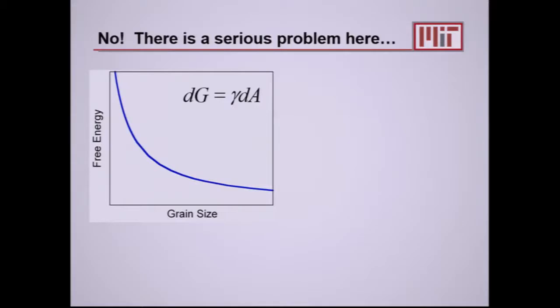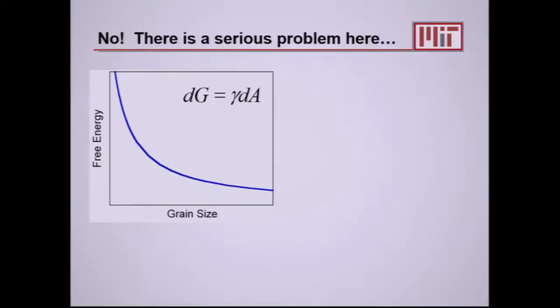And there's a serious problem here. And in fact, it's the oldest problem in all of material science. It is that this is an unstable structure, and those grains are going to grow, right? So, J. Willard Gibbs, your hero and mine, father of us all, right? Chemical thermodynamics. J. Willard Gibbs, back in the Victorian era, had nanotechnology all figured out, at least as far as this problem is concerned. You know, he told us that if we add interfacial area to a material, if we add grain boundaries to a material, those things have a positive energy penalty, akin to a surface energy.